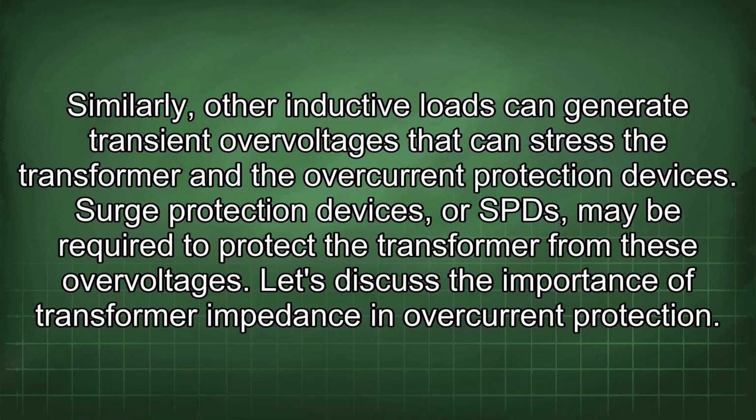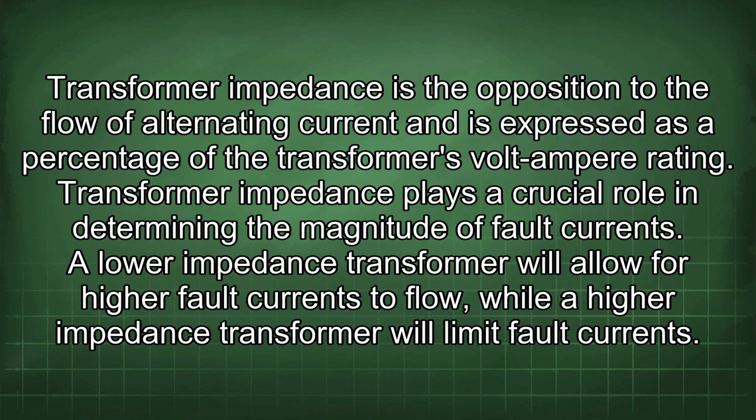Let's discuss the importance of transformer impedance in overcurrent protection. Transformer impedance is the opposition to the flow of alternating current and is expressed as a percentage of the transformer's volt-ampere rating. Transformer impedance plays a crucial role in determining the magnitude of fault currents.